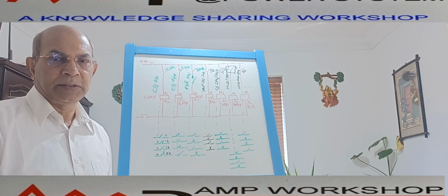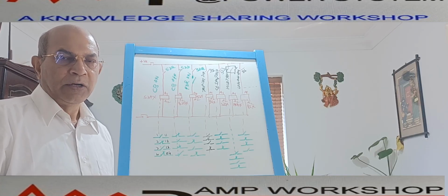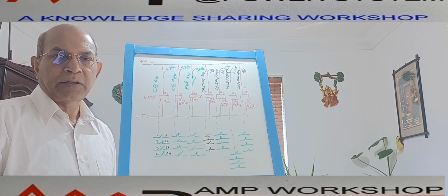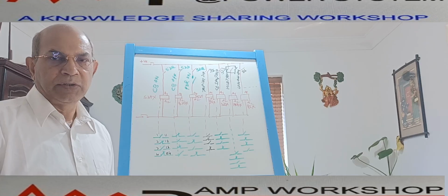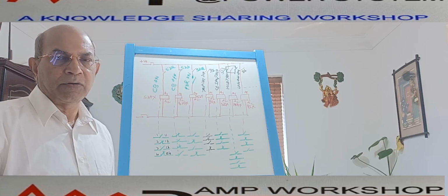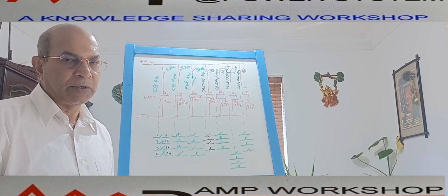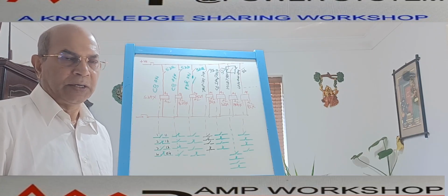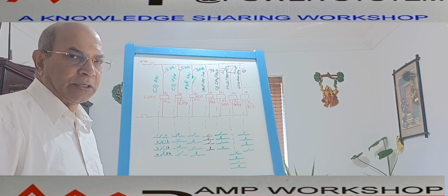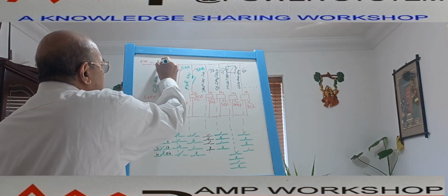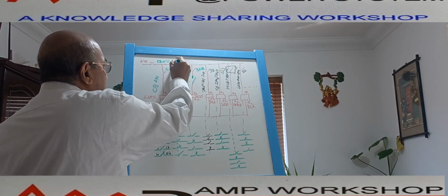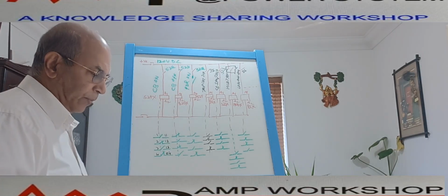This relay can be an AC relay or a DC relay. As the control supply is DC, that's why we are using the DC relay. And if the control supply is AC, then we choose the AC relay. The relay control voltage or the coil voltage we decide based on the control supply application. In our case, we are considering 120 volt DC supply. So all the auxiliary relay coil supply will be 120 volt DC during selection of the relay.